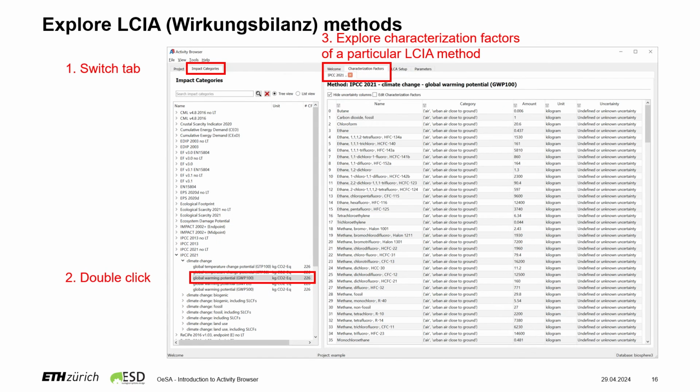At the same time, if you switch the tab on the top to the impact categories, then you would be able to see all kinds of impact categories available to you by default from just the imported ones, where we pressed this button, default impact categories. If you double click on one of the impact categories and choose the tab characterization factors, then you would see the different biosphere activities and their amount. So the amount is the characterization factor.